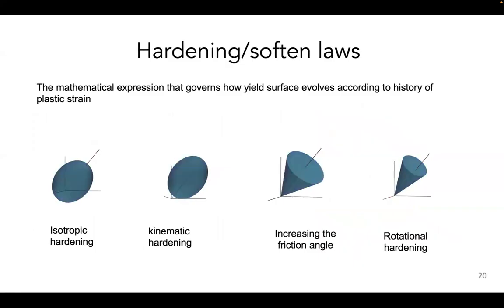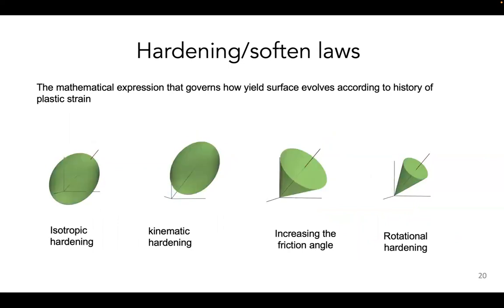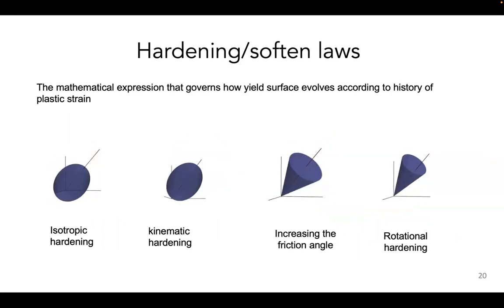Okay, so the hardening law is another ingredient. Just bear with me. This is like a cooking show. I just show all the ingredients. There's a turkey, there's a potato, and it could be quite boring. But the hardening is another one. It tells you the governing evolution of the yield surface according to some history of the plastic strain.